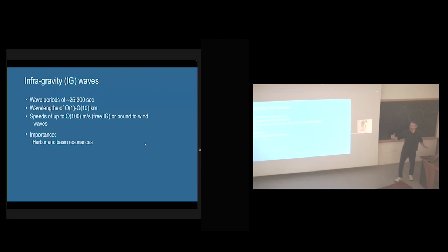They can oscillate if the scales are a few kilometers. You can have a port and a pier area of 3 kilometers. They can seiche inside, and then they really bother ships. They can alter the breaker line location, so they affect sediment transport. They affect satellite altimetry, and we show something that Fabrice was doing there. You can see him here, he's a star of this show.